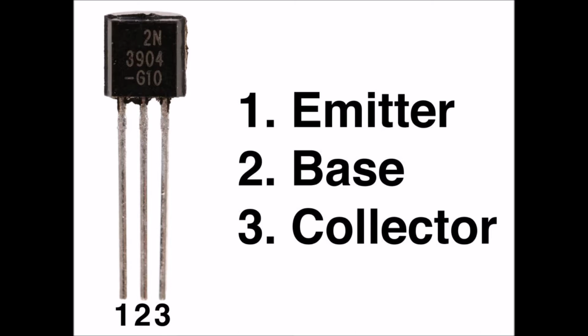The alpha for any transistor is always less than 1, because whenever we apply a signal to the input, the base bleeds off at least a little current from the emitter before it shows up at the collector.